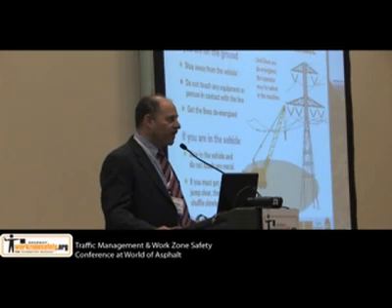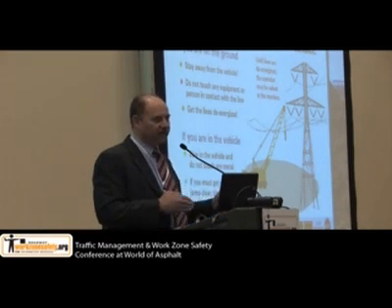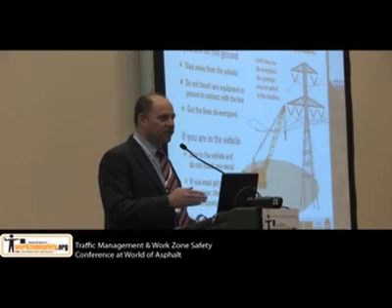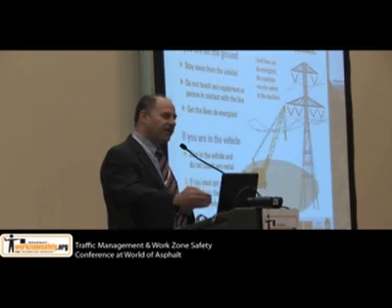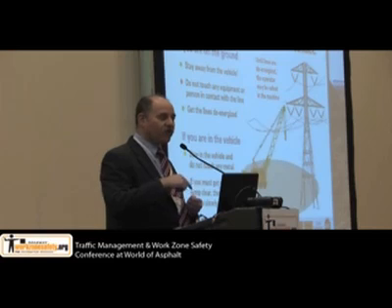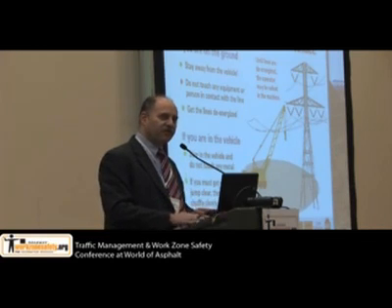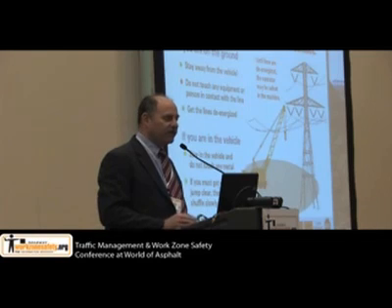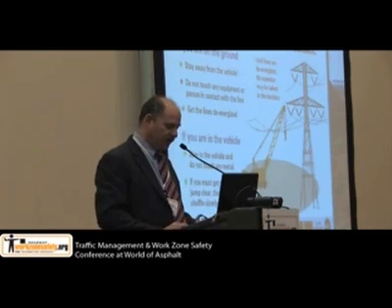Does everybody understand why you do that? Because the amount of electricity in the soil decreases rapidly from where the vehicle is. So if you step out and take a step, then the electricity can arc through your body from the higher area to the lower area. But if you're shuffling slowly away, you don't create as much difference between your feet, so you don't have the arcing.